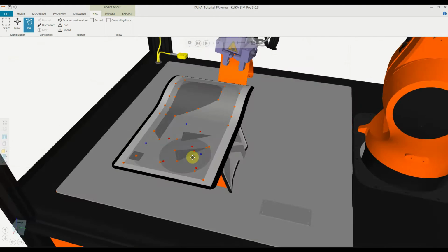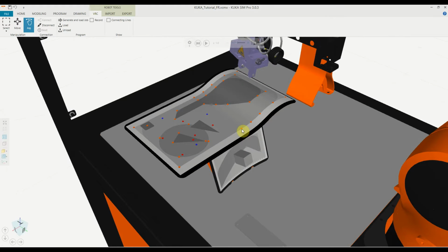So what I'm going to do actually is I'm going to choose this point as an origin. This is going to be our X direction, and this is going to be our Y direction. So what we need to do is we need 3 points. The origin point, which is here, our X and our Y direction. And as we do that, we're going to move perfectly straight in here, as well as in here, which is going to be the same line in here, like in here. So you will see everything after teaching the frame is done.